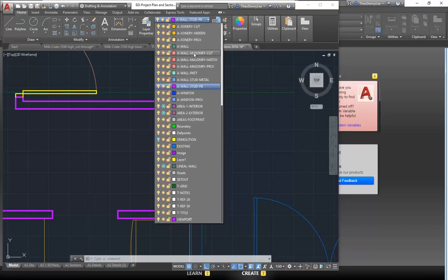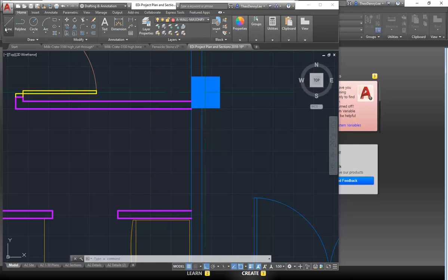So I'm going to go to my correct wall layer and just draw a line and then offset, I don't know, 100 from there, and then offset again to 900 to create my door opening. And so that is always the process you should use for every window and door you ever create in AutoCAD. Draw the wall first and then make your opening.